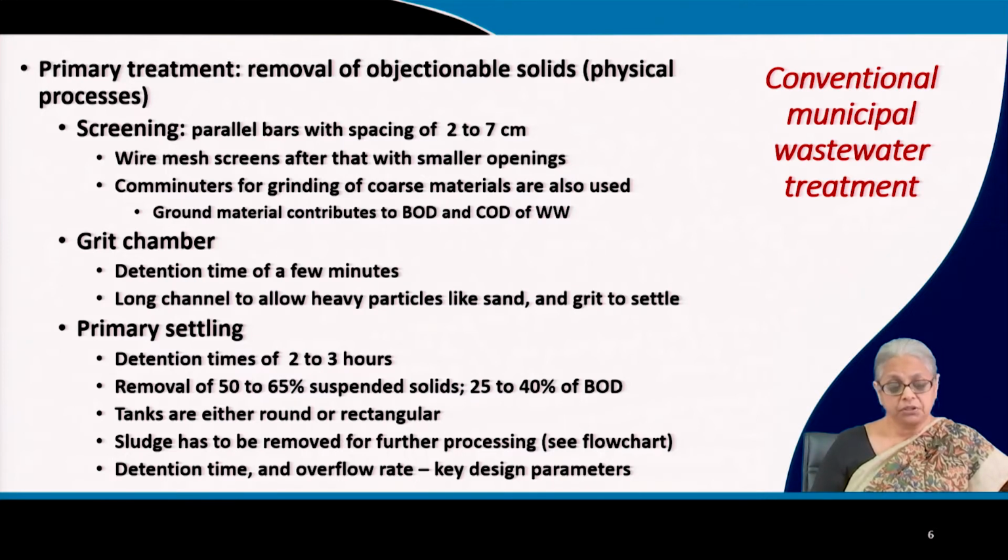So this material, because it is biodegradable to some extent, can encourage the growth of microorganisms. We also have a grit chamber. This grit chamber has a detention time of a few minutes. It's a long channel that will allow discrete, which means heavy particles like sand and grit, to settle by gravity.